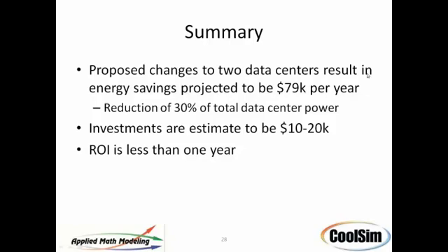All right. What was the rule of thumb with 10 degrees Fahrenheit and 19% savings? The rule of thumb that is used is for every 1.8 degree Fahrenheit of cold air supply increase, the efficiency of the cooling system increases by 3.5 points. 3.5%. Yeah, 3.5% for every 1.8 degree Fahrenheit increase is the rule of thumb.